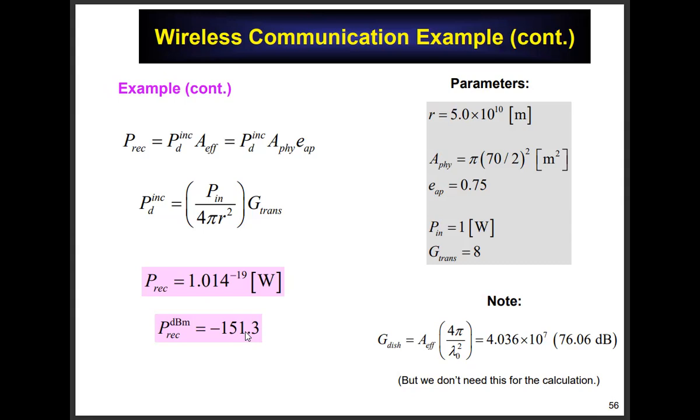Now, because it's such a weak signal, the signal-to-noise ratio is going to be terrible. If you've taken communication theory, you know that the communication data rate is related to the signal-to-noise ratio, right? That Shannon formula. So with this kind of low power, the SNR is going to be terrible, and maybe the bit rate could only be something like, who knows, a few bits per second. Maybe, but they can still process data coming from the CubeSat that far away.